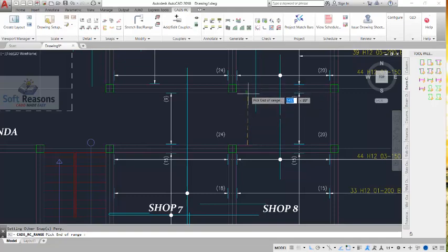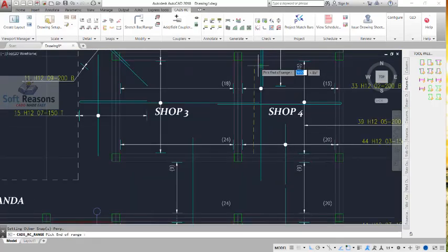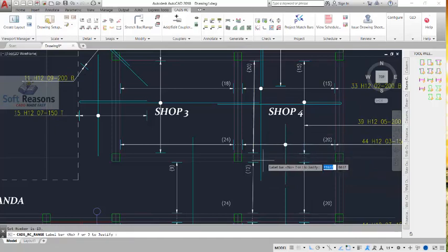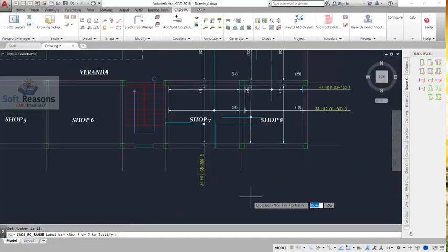So you just pick this point, which is second point, enter, and then enter again. Before you finish, come over to this provisions, pick that, enter, and then all the way to this point, pick it and enter as well. Enter again. So you just have to enter the last time to have it placed successfully.